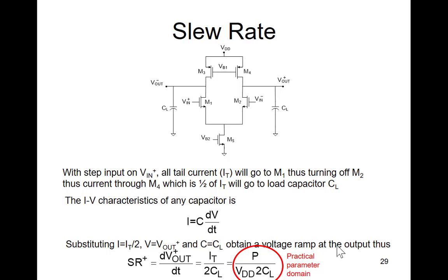Not necessarily. You won't kill your gain, because the gain was only V excess bias. But if your bandwidth goes up, your integrated noise will go up, so your signal-to-noise ratio may deteriorate. So it's not always advantageous to make more GB than you need. Make sense?